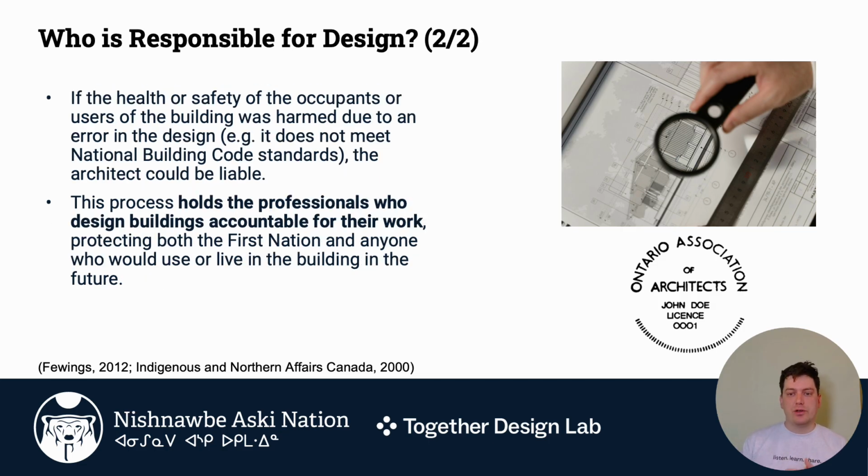This means if you're working from and building to a stamped drawing, that any of the problems of health or safety or errors in design, by which we mean not meeting the required code, is the responsibility of who has stamped that drawing, and they're then accountable for those drawings. And so you want to make sure when you're choosing a design that it is stamped, to make sure that that responsibility and liability isn't yours or isn't the First Nation's, but instead falls on the professional who created the drawing.